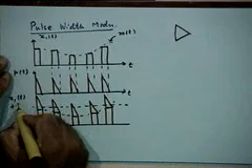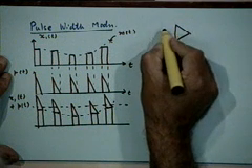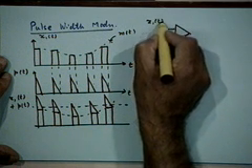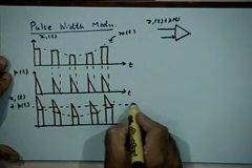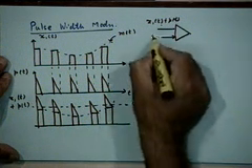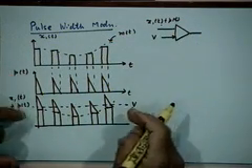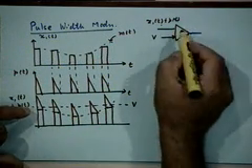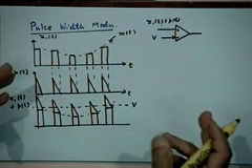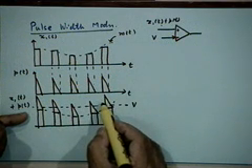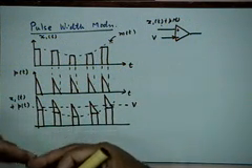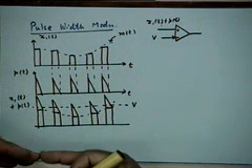One of those inputs is this signal, which is x1(t) plus p(t), and the other input is a reference voltage, which is equal to this constant voltage, let us say V. So, the output of the comparator will be a positive output when the input signal is above the threshold value, above the voltage V, and will be either 0 or negative depending on how you design the circuit. Let us say it is 0 when the input voltage is less than that.